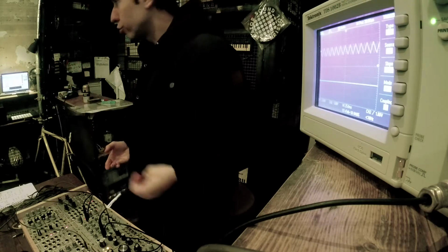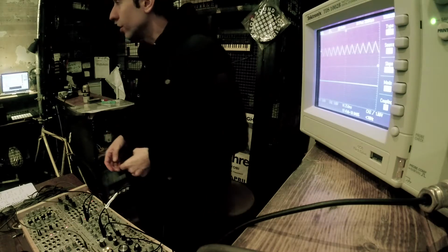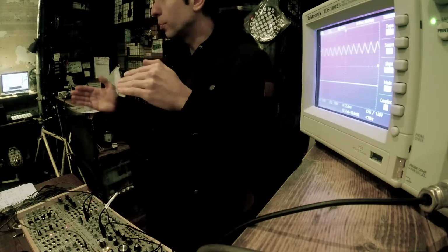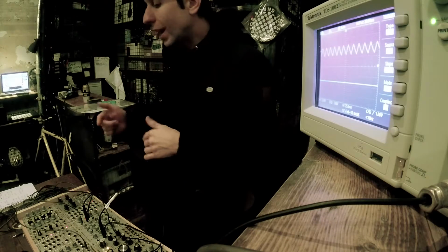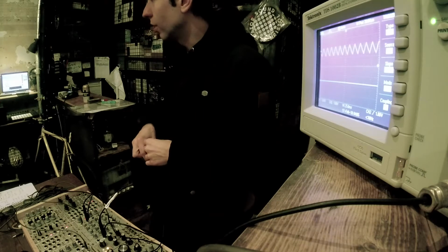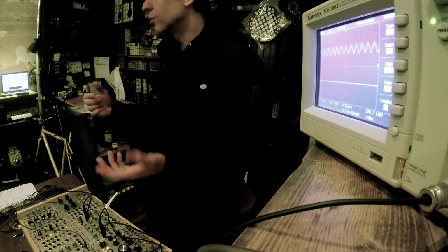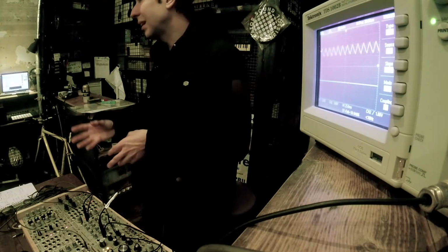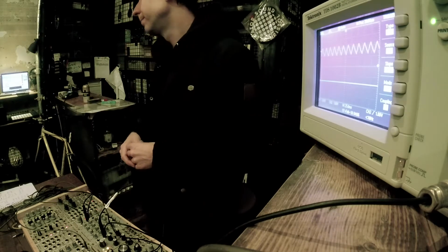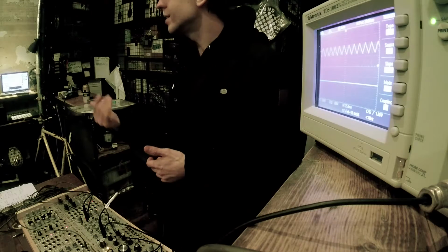But this is technically not trivial. I mean, it's easy for us to explain and to think of and to imagine, and digitally it's not even that hard, but as far as I understand, in electronic circuits, this is a problematic thing. Yeah? So, and this is what a low-pass gate is. It's a kind of a non-kosher filter with an anomaly in essence, because it acts also as a VCA. That's why people talk about, okay, so it's a low-pass gate, it's a bit like a filter and a VCA. So as you decrease the frequency, you decrease the volume as well. That's the kind of thing that happens in a low-pass gate. Right, okay. And that's why they call it gate, because it kind of gates out the signal.